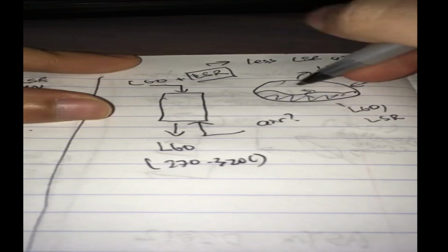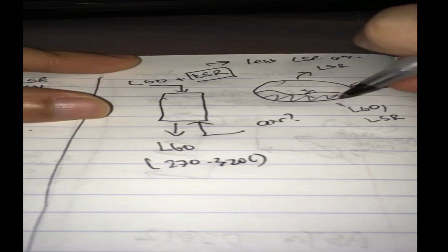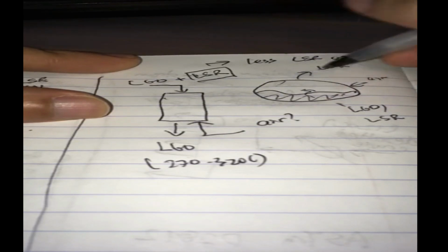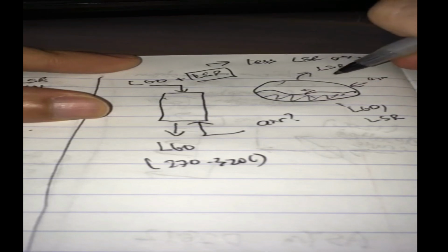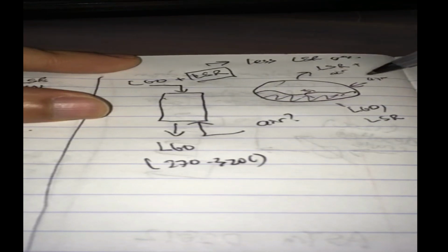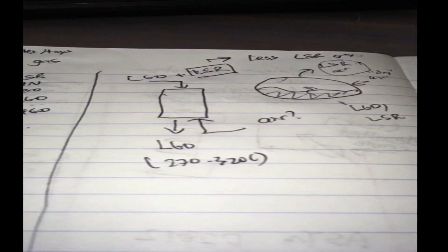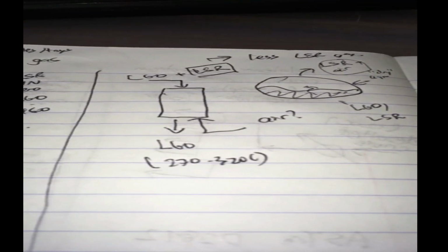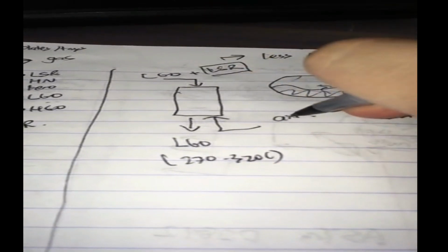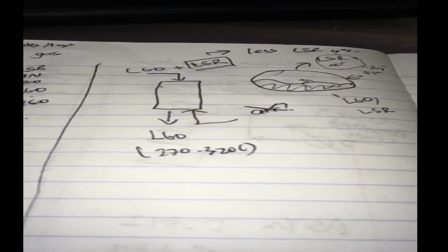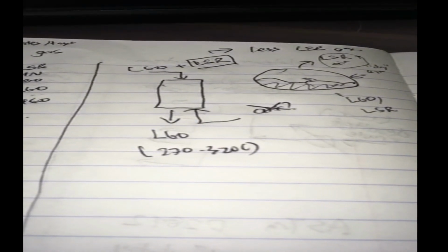But if this thing is so saturated in light straight run gasoline, you can't evaporate much anymore. So you need some kind of diluting gas or air to get it out. So you blow air inside, dry air, so-called dry because it lacks light straight run gasoline. So it blows in and comes out, light straight run gasoline plus air. This is a vapor. Is that a good idea? Not really, right? So air is definitely out of the question, because air plus hydrocarbon vapor equals boom. Not good, not good.